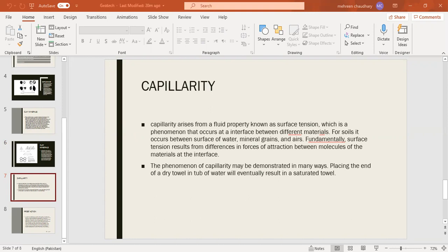To illustrate the effect of capillarity in soil, we can use a small diameter glass tube to represent the soil grain. Capillary tubes demonstrate that the adhesive forces between the glass wall and water cause the water to rise in the tube between the glass and the tube wall. The height of rise is inversely proportional to the diameter of the tubing. The smaller the inside diameter of the tube, the greater the height of capillary rise.